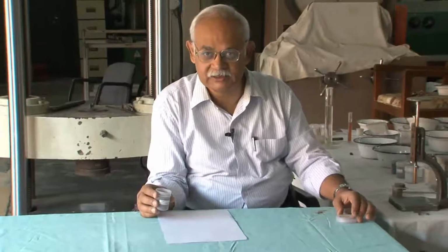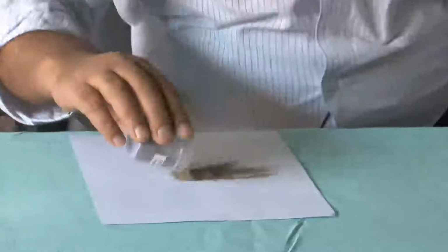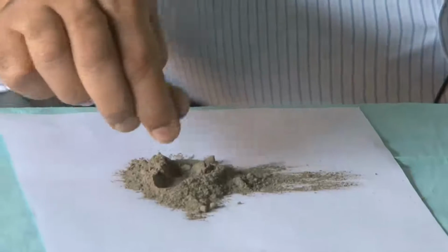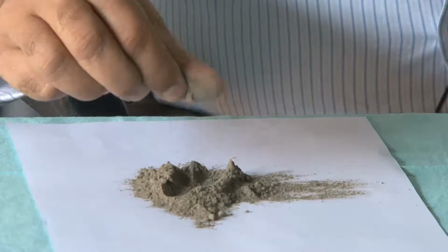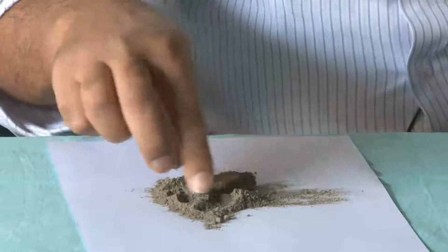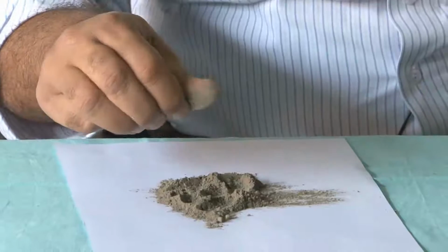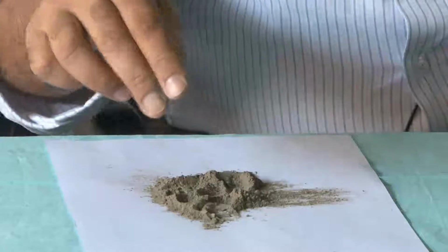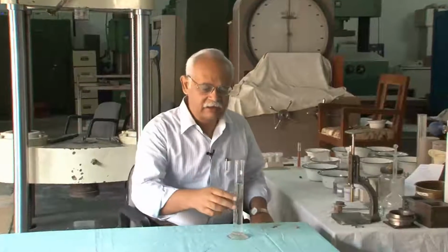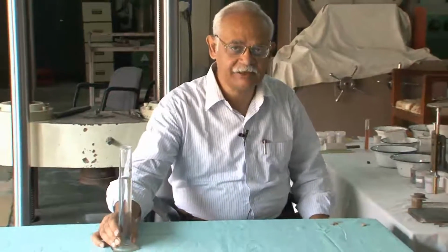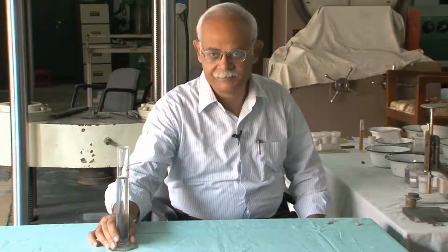Now, we come to the most important and perhaps most expensive of the construction materials in concrete, and that is cement. So, this is ordinary Portland cement, that is the one that we use for most of our concrete construction, maybe in mortar, plaster and so on and so forth. It is grey in color, is very fine, and we will need to study its properties in great detail before we can actually use it. And lastly, this is water, which provides the basic ingredient for the hydration of cement.